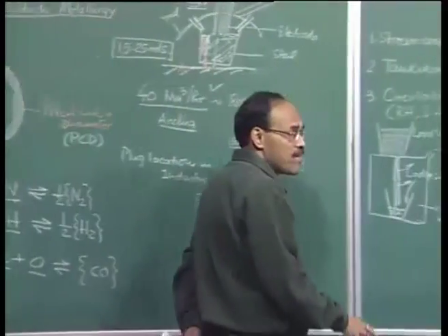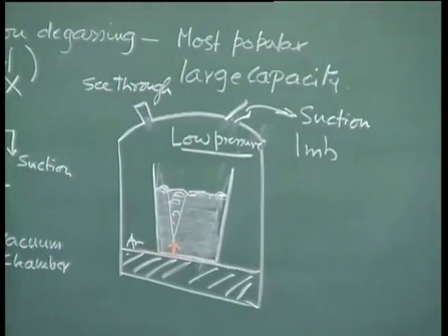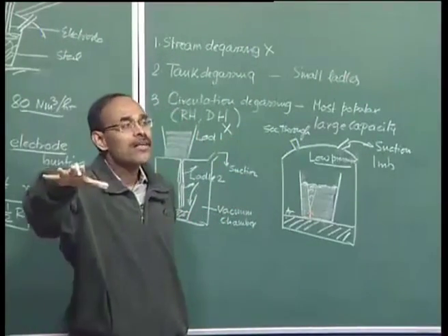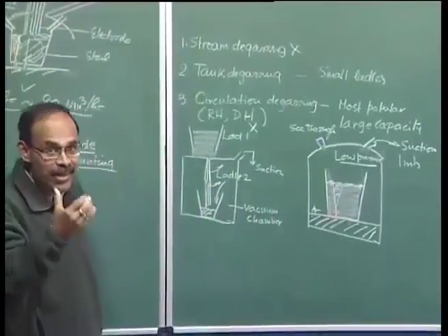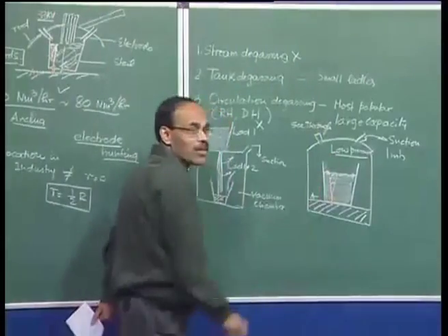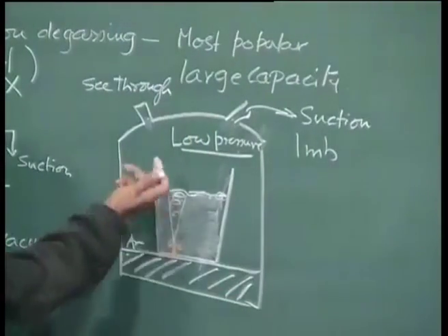We must understand that without argon, what is the scenario that we are going to have? We are going to have molten metal covered completely by slag. So we want to bring molten metal in contact with the vacuum or the atmosphere, and as a result of which we have to blow in argon.